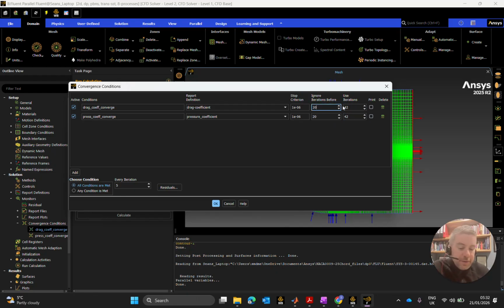And for that matter, I'm going to drop that down to 18. By 18, any initialization that I would have done on all my cell centers prior to running the calculation should have, I'm using an upwind scheme, should have filtered their way downstream and thrown me enough off kilter not to have 42 successive iterations where I'd be below my convergence or my stop criterion here. And maybe I'll drop that down to checking that again every 3, that's half a 6.